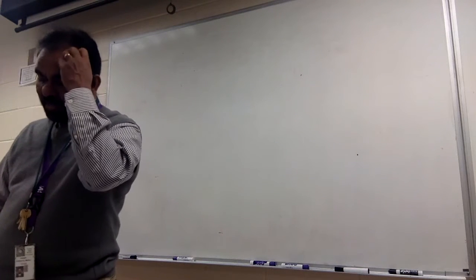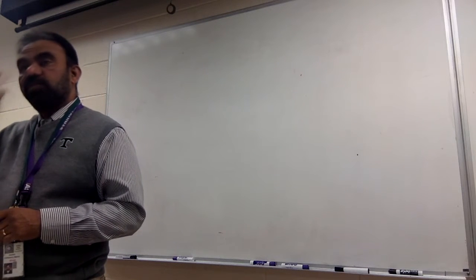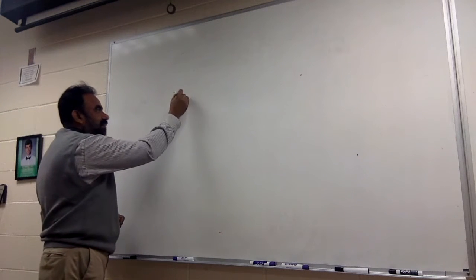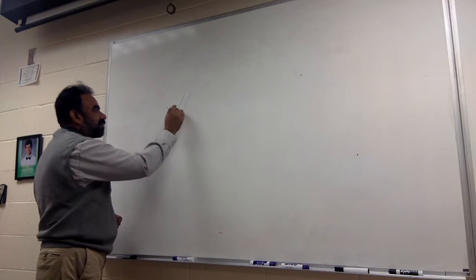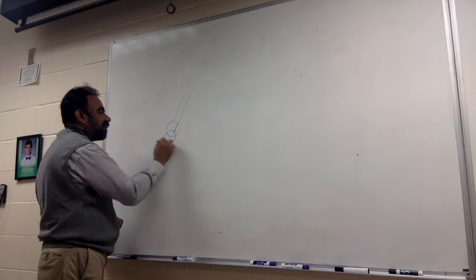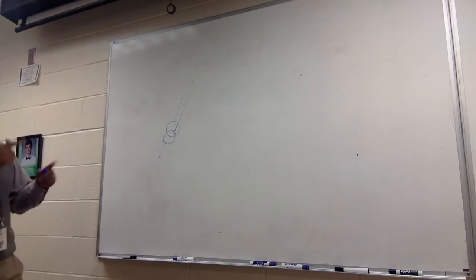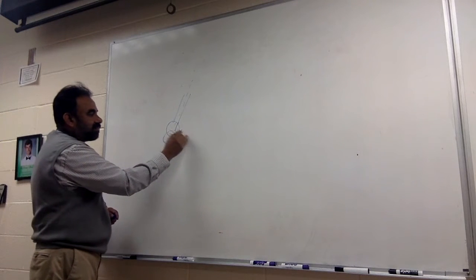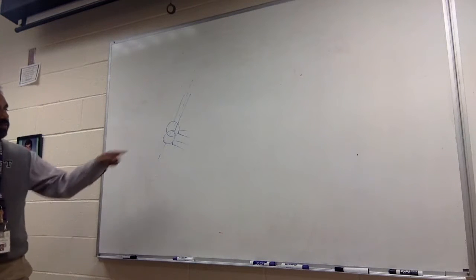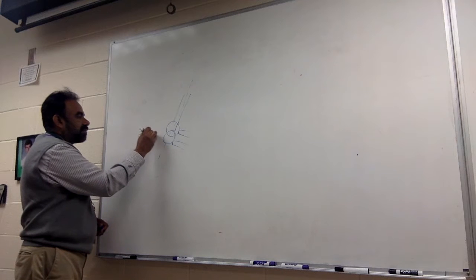So we were talking about generators in the last class, all right? AC generators. So the AC generators use slip rings, right? That's one ring, that's the next ring, and that's the axis of the generator. As it is spinning like this, the two brushes, brush number 1 and brush number 2, tap out the voltage that's coming out from these two slip rings. These are slip rings.